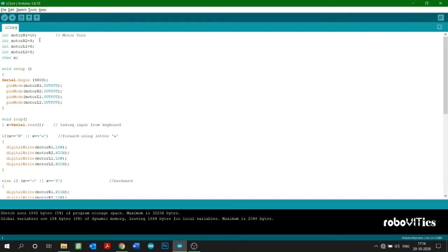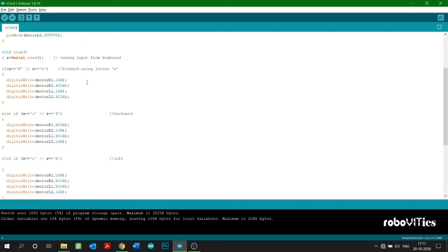This is in case the left wheel was rotating in the opposite direction, going backwards instead of forwards when we press W. If both the wheels were going backward, do the same changes for both. But right now I took the case of only the left wheel, so just make the changes for the left wheel if required. Otherwise, 6 and 5, this was our initial condition, which would be perfectly fine. This is our case if we want the bot to move forward.